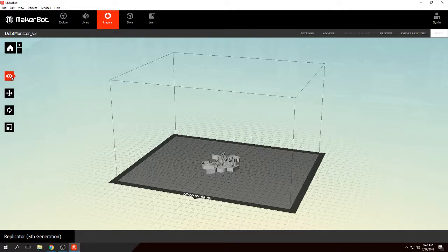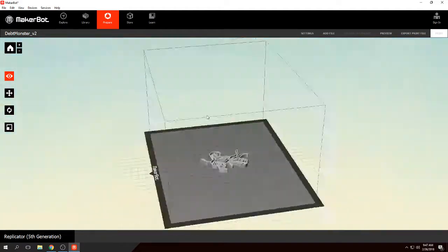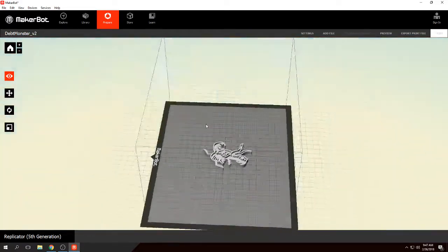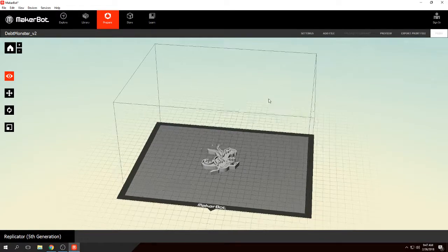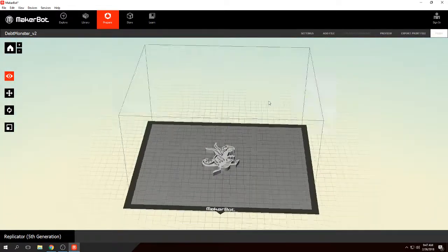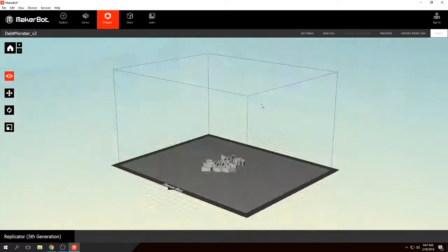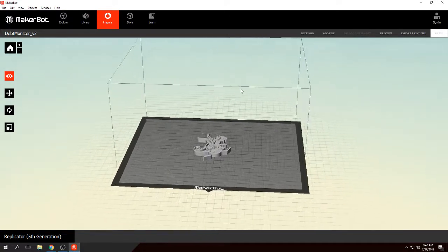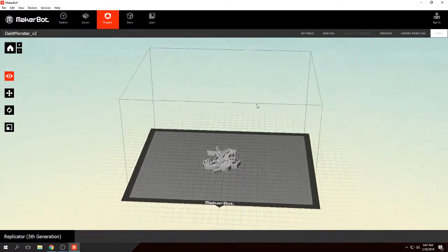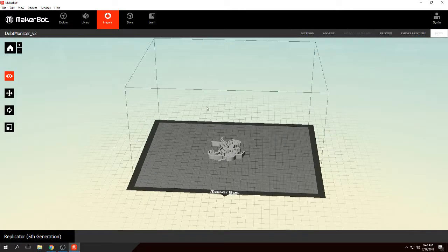While you have the View tab selected, left-click anywhere in the viewport and drag will allow you to orbit. Right-click anywhere in the viewport, or any of the selection tools on the left-hand side, will also orbit. Middle mouse button will pan. Scroll wheel up is zoom in. Scroll wheel down is zoom out.